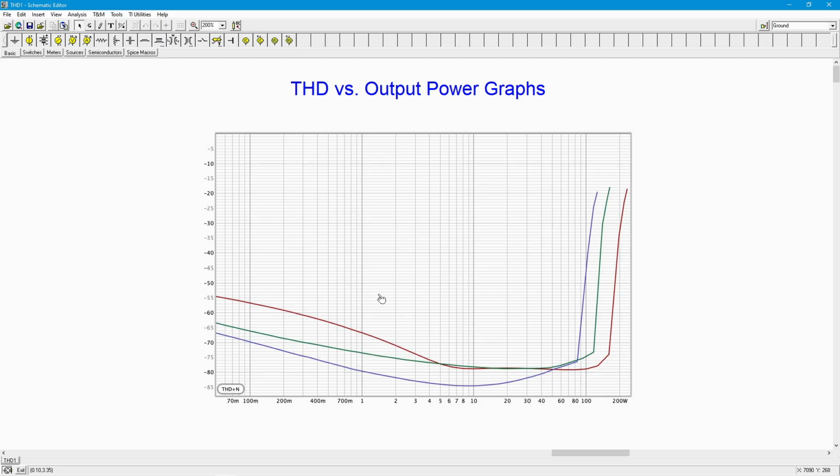Maybe it's not the wisest move to sink a lot of money into improving an amplifier. Let's say you got something that's 0.05%. Do you want to spend a few thousand dollars to get from 0.05% to 0.009%? That doesn't make a lot of sense to me, especially when your loudspeakers, depending on the amplitude and the frequency, might be producing a couple of percent THD. All right, so that's just one little piece of the puzzle. Your amplifier is just one part of the whole thing.